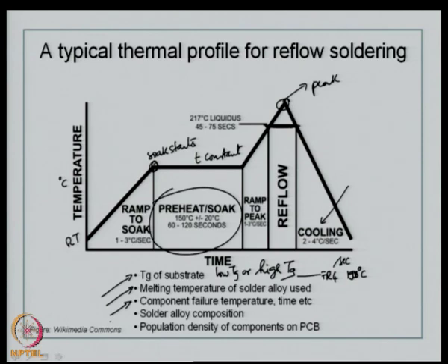In certain cases you have a problem. If you look at the entire bill of materials, your component list, there will be one component which says this component should not exceed 230 degrees centigrade for more than 45 seconds. The component is vulnerable to such a residence time during soldering.